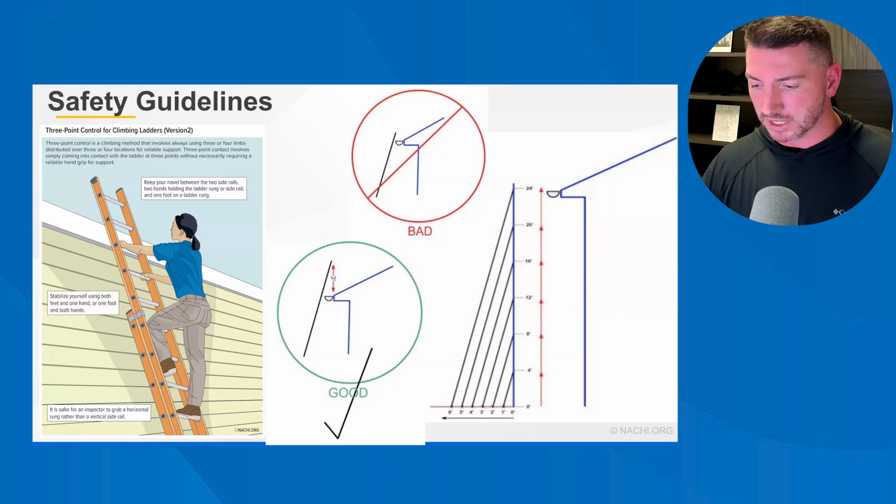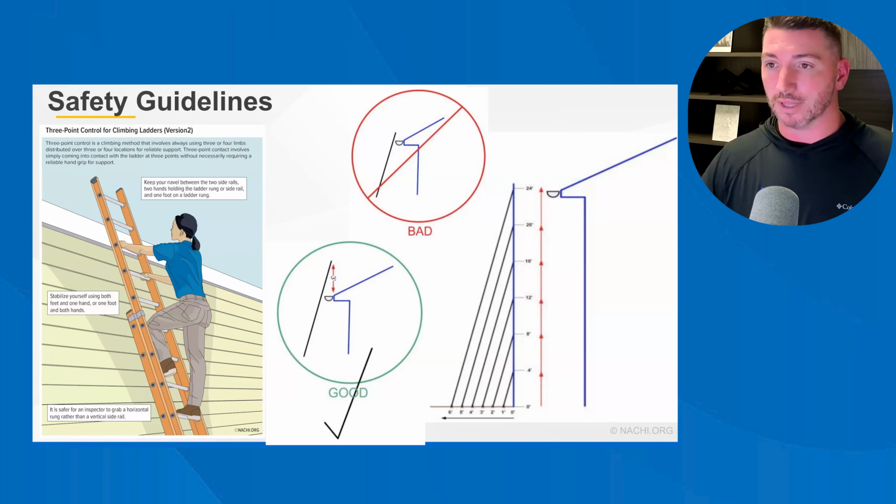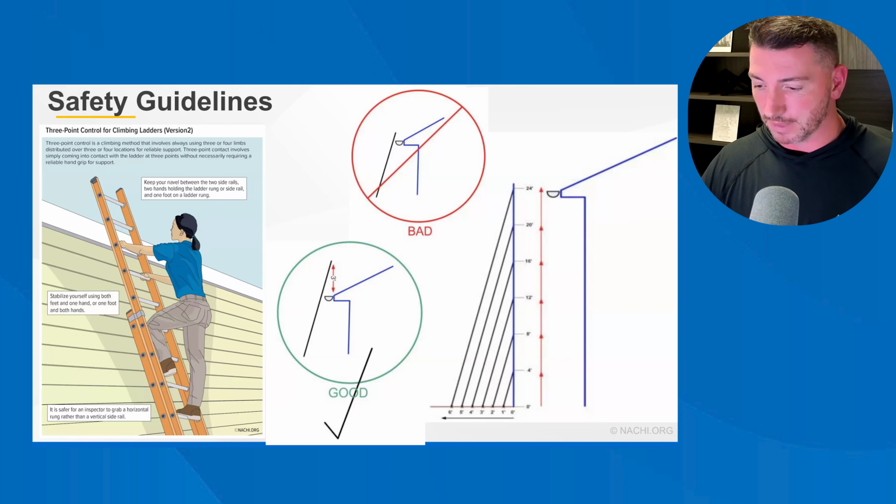So misuse or mistakes can result in death. Please keep all the ladders and tools at least 10 feet away from live power lines. Again, as many things as they mentioned for safety, I've been doing this long enough that I know stories for pretty much every safety precaution. I know somebody that hit the electrical line and then got kind of blown off their ladder and broke their ankle. So these are all real things. They're not just in here just for liability's sake. It's legit.